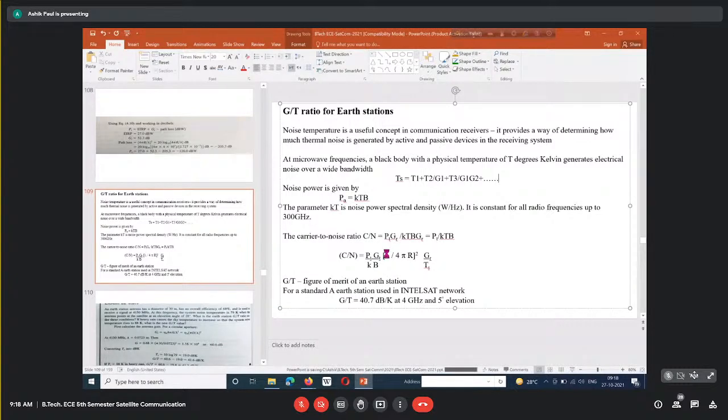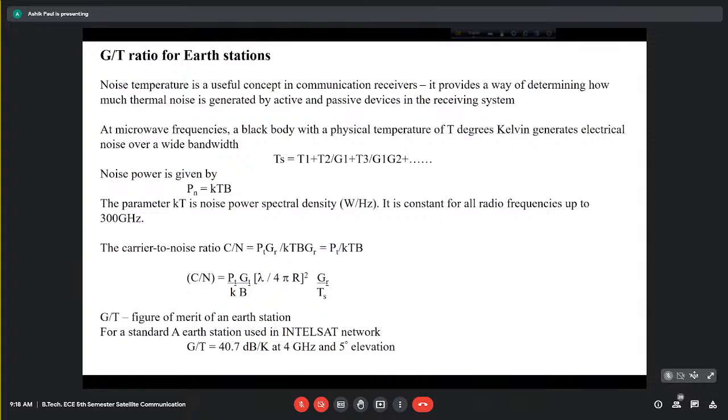in case of a typical communication receiver, which may be of a superheterodyne type, the gains of the individual stages are very high, because we are dealing with a very weak signal. Under that kind of situation, as we go to the higher order terms, the denominators become extremely big, because we are having the product of two large values.